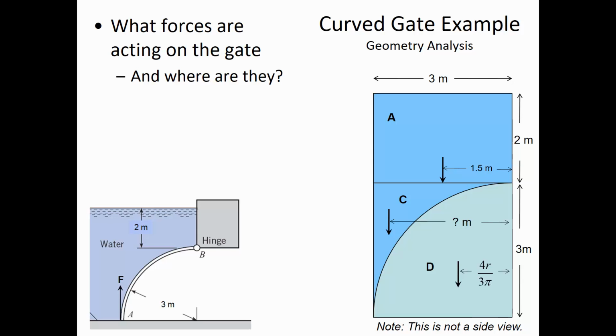So let's first have the force A is going to be the volume times gamma. And you can just by inspection see that that is going to have 2 meters by 3 meters by 4 meters as its volume. Okay, so 2 is the height of this box, 3 is the width, and then it's 4 meters into the page.